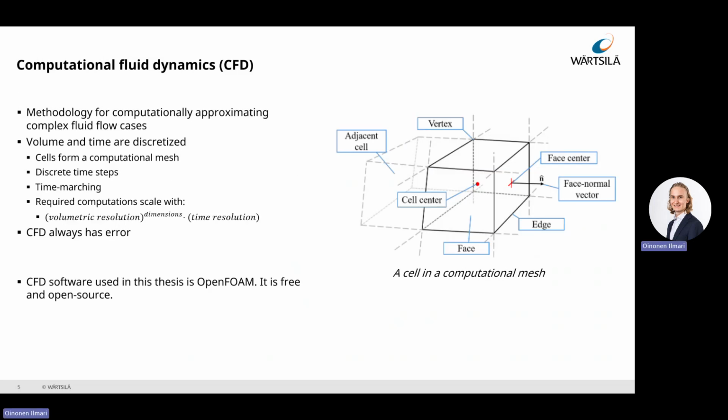In this thesis, CFD is used as the method of modeling the fluid flows. In CFD, complex fluid flows that cannot be solved analytically are instead solved computationally in an iterative manner. The control volume inside of which the fluid flow is housed is divided into a large number of individual cells that constitute a computational mesh.